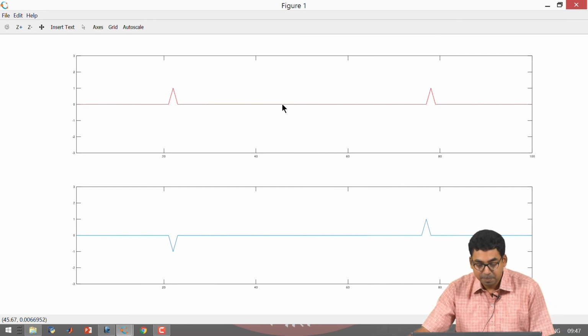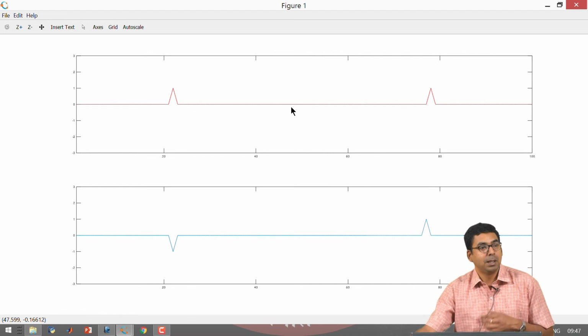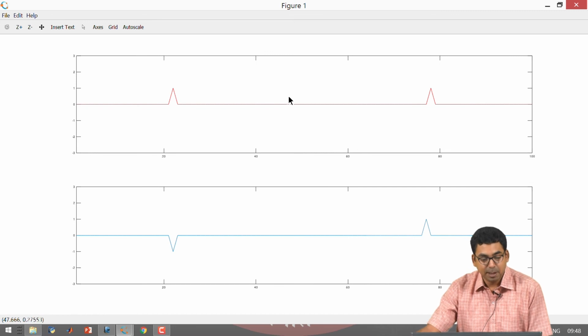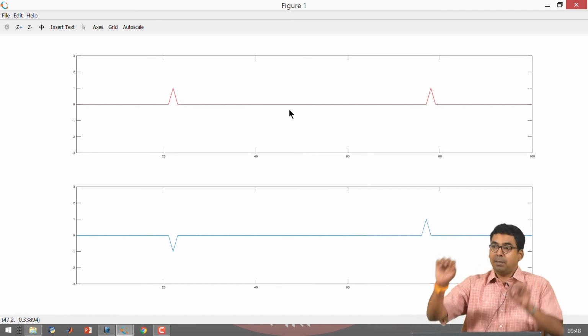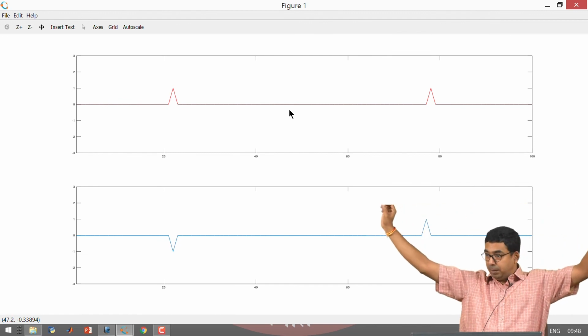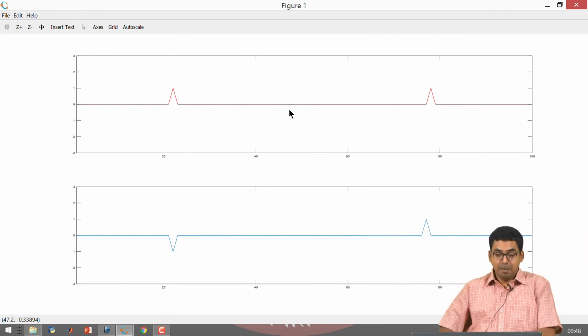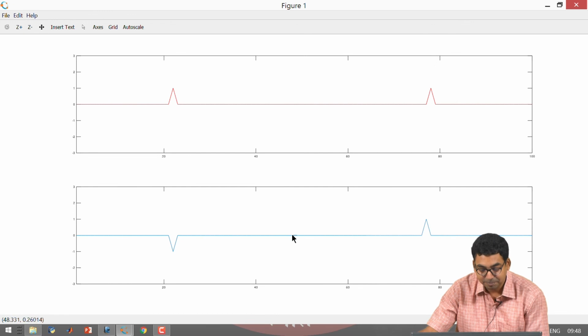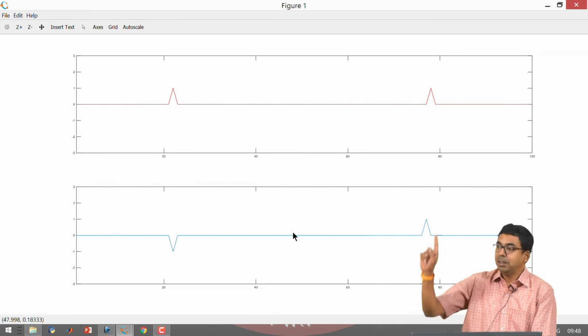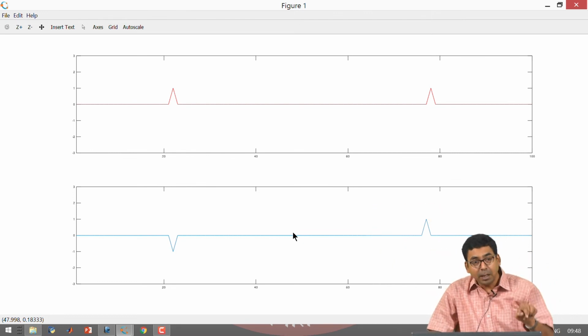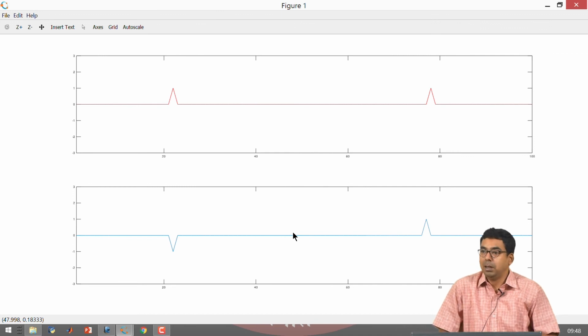Next thing that I notice is I had set my source in the center. Regularly in a transmission line you may not be able to do this, but for our understanding we could do this in a program, right. I set an impulse at some instant of time and the impulse traveled to the left and to the right in the transmission line. Okay. So, the voltage is going from the center to the other side, but notice the current, it is travelling to the right side with a peak at 1 and it is travelling to the left side with a peak at -1. First of all, this information was not available to me before when I was solving the wave equation, right. Now, this is a new piece of information, correct.